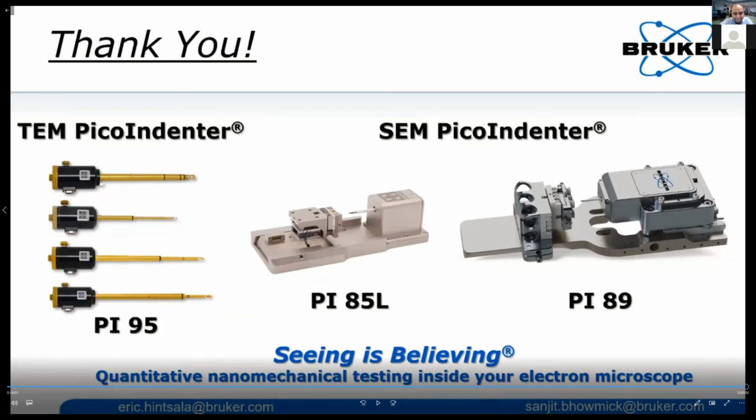For fracture toughness measurement, you need to measure the crack length, and you need to know the modulus and the hardness. With in situ SPM imaging, you can do that very nicely with our system. But the models that we use to measure fracture toughness have certain assumptions. If you validate those assumptions, then your measurement is right. For example, the crack length has to be a certain length compared to the width of your indents.